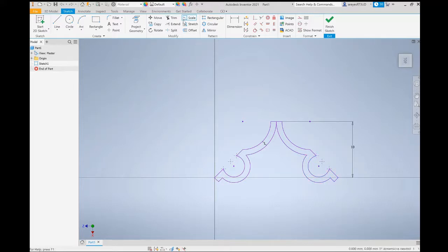Let me just make my selection. So you select, and then you scale. As you can see, since I already inputted the dimension, it's locked into this 10 mm. But if you decide to scale up or make the object larger, you can relax the dimension if you intend to adjust it. The geometry is constrained to the other geometry, so you can remove the constraint of the dimension.